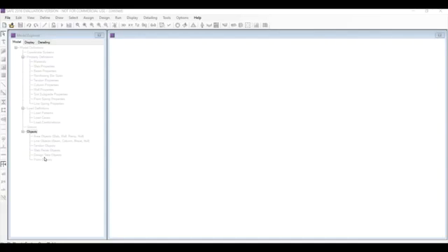We need to have all these base reaction values so that we can assign those load values to the mat footing. Before designing a mat footing, we will assume our own data and do the design. So let us assume a mat footing of 18 by 18 meters, and we will be having 4 by 4, that means 16 columns in the mat footing. And let us give our assumed column dimensions.